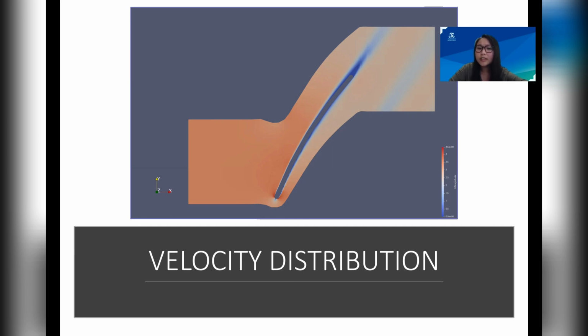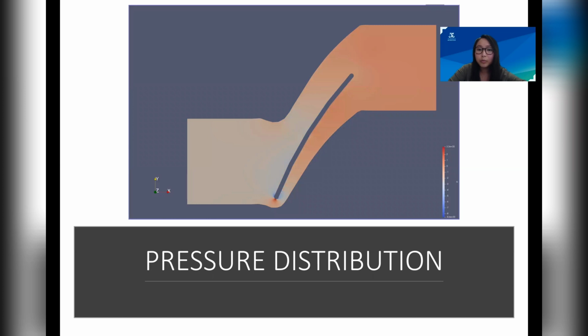As we are evaluating a single compressor blade, a pipe cyclic boundary condition has been imposed to mirror the environment in which the blade sits in, a compressor. Here you can see the wake developed by the blade. We can see that velocity at the wake is much lower compared to the free stream velocity. Conversely, the pressure in the wake of the blade can be seen to be higher, consistent with Bernoulli's principle. These results are also consistent with the expected behavior of a compressor blade.